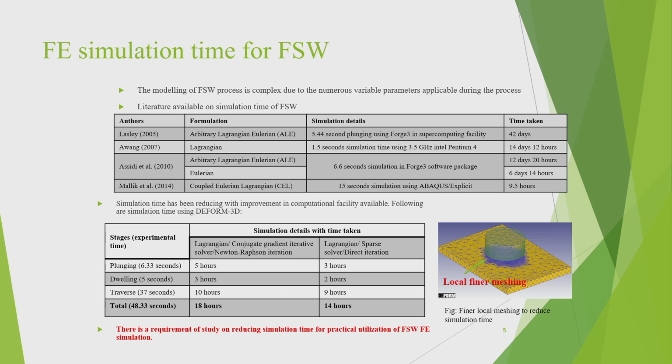Now here in DEFORM 3D, what we did was plunging for 6.33 seconds, dwelling 5 seconds, traverse 37.37 seconds, and total time was 48.33 seconds.